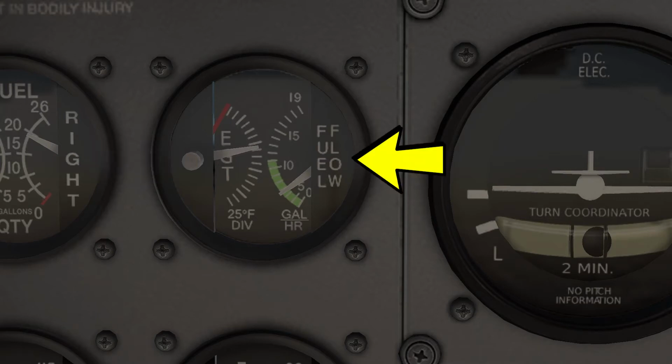Fuel flow indicator. This indicator displays how many gallons per hour of fuel the engine is consuming. Leaning out the engine at higher altitudes can prevent engine problems and save an extraordinary amount of fuel. For example, if you flew the Cessna 172 from Stewart on full rich, you would run out of gas by Atlanta. If you lean the engine out, you will run out of gas by Chicago.